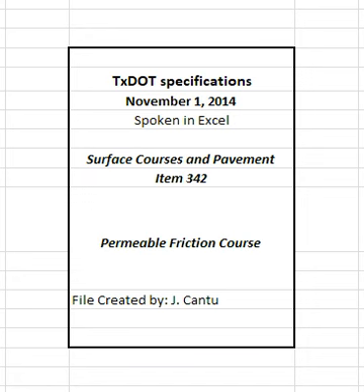2.5.3 Lime and liquid anti-stripping agent. When lime or a liquid anti-stripping agent is used, add in accordance with Item 301, asphalt anti-stripping agents. Do not add lime directly into the mixing drum of any plant where lime is removed through the exhaust stream unless the plant has a baghouse or dust collection system that reintroduces the lime into the drum. When the plans require lime to be added as an anti-stripping agent, lime added as mineral filler will count towards the total quantity of lime specified.